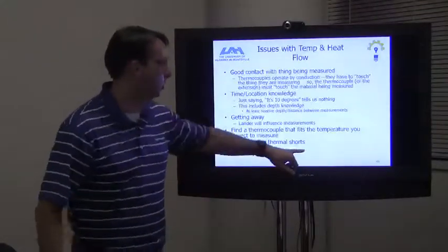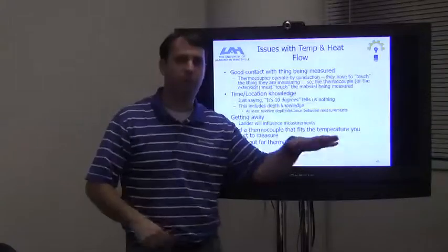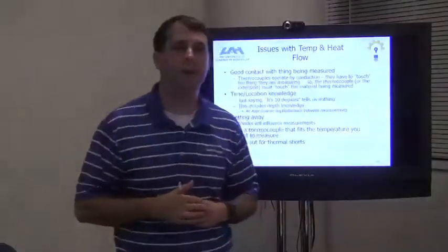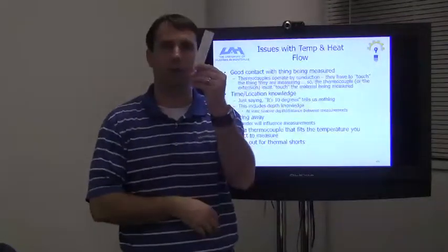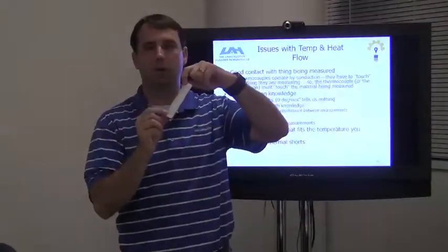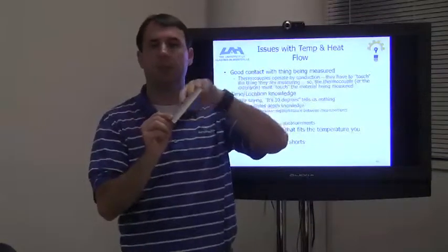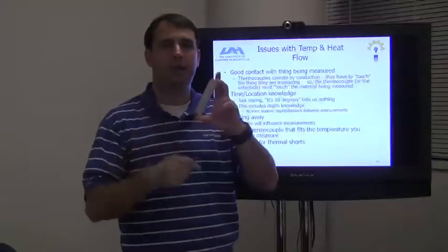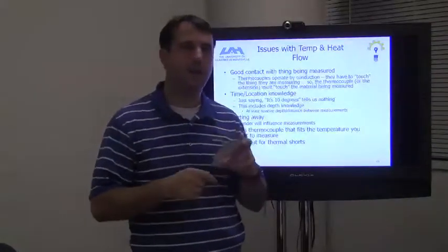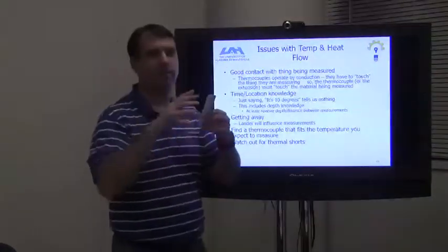Watch out for thermal shorts. A thermal short, it's not a short person, or short thermals or something. But a thermal short is what it sounds like. This is a piece of metal right here in my hand. If I put a hot thing here and a cold thing there, the temperature is going to conduct through this metal.